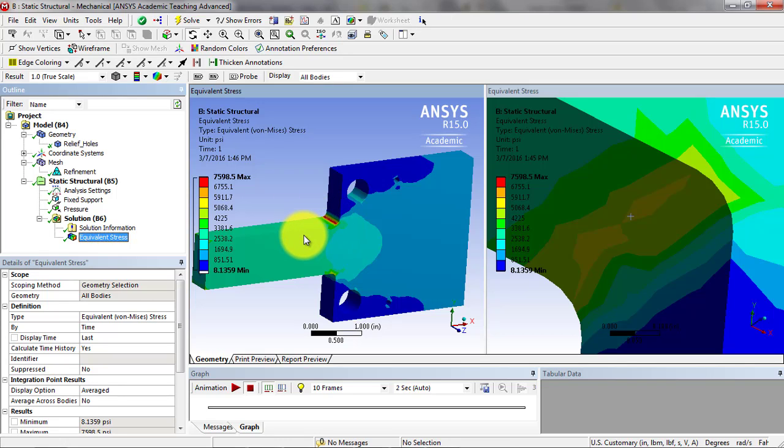If everything else is working, you've got plenty of time, and you've got the computational power, we could just make this whole part have a finer mesh, and I showed you how to do that with the glass in the last example.